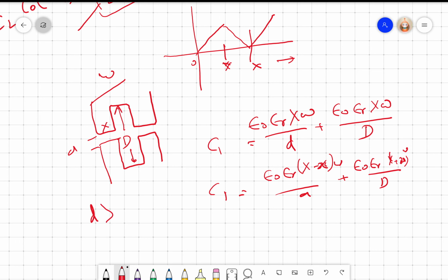we make small d much smaller than capital D. For example, capital D may be centimeters, and the small d will be micrometers, right? We take a 100 micrometer air gap and make the other half a centimeter. Capital D is 5 millimeter, and small d is 100 micrometer, right? So this can be neglected, and you will get a very linear transducer.